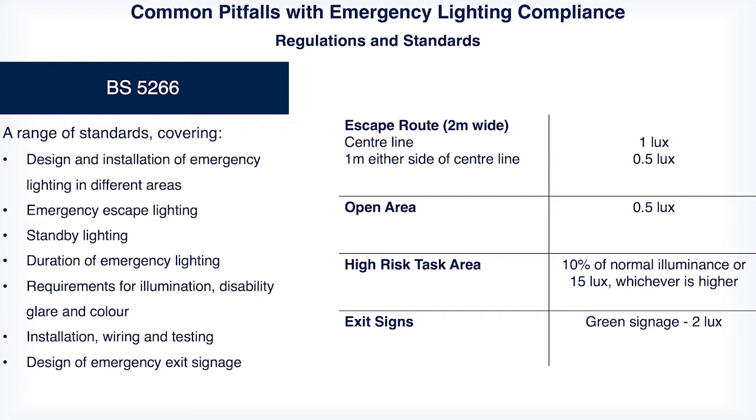So that's quite a significant jump up, and requires real involved design work with the luminaire manufacturer to make provision for that. We have had experience in our business of a number of linear or high bay lighting products, and every one of them in that area might need to be an emergency lighting product to provide that kind of coverage for what the fire risk assessment determines is a high risk task area. The definition of high risk task areas can be quite extended.